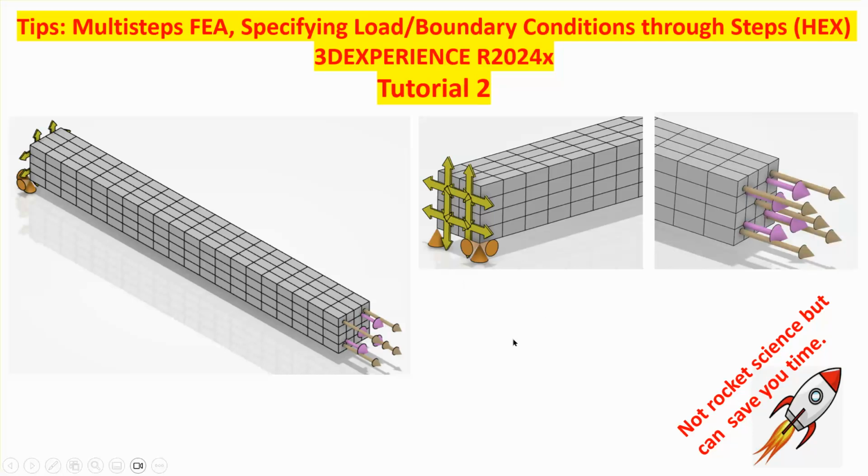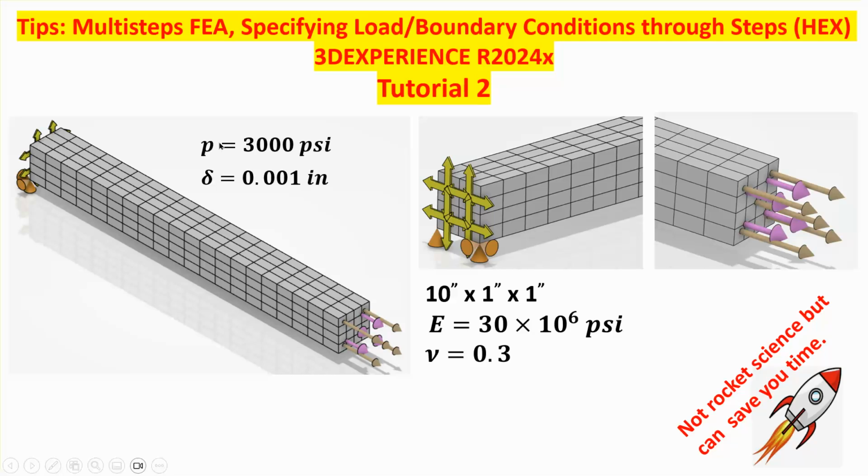Now, the right-hand side is a combination of pressure or displacement, as was mentioned in tutorial 1, and I'll repeat it again. First of all, it's assumed to be 10 inches long, 1 by 1 cross section, made of steel, with Young's modulus given here, and Poisson ratio 0.3. Of course, I can use 0 as a Poisson ratio, but that's okay. We leave it as 0.3.